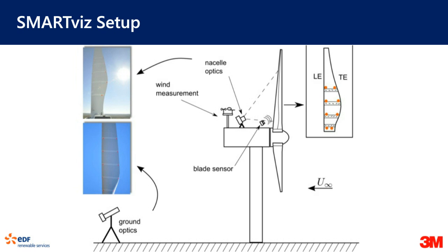We can really look and understand where the flow separation is happening. By doing this thorough analysis on an operating turbine, we can completely figure out the best position to install the vortex generator for a particular turbine and blade model. That helps us to differentiate and make sure that we have the most efficient output from a VG installation.